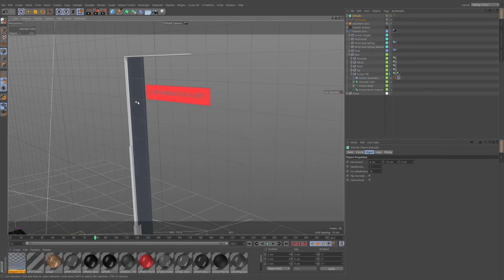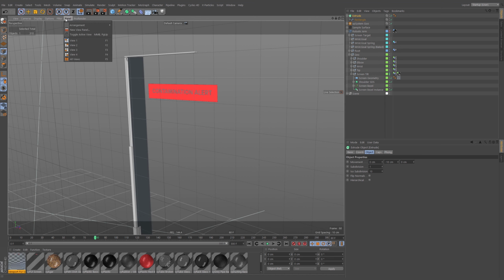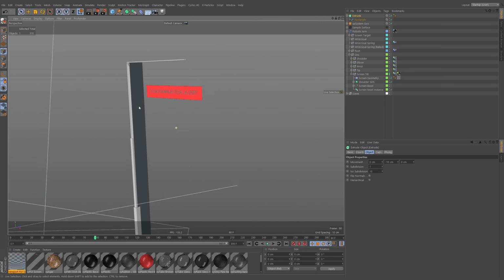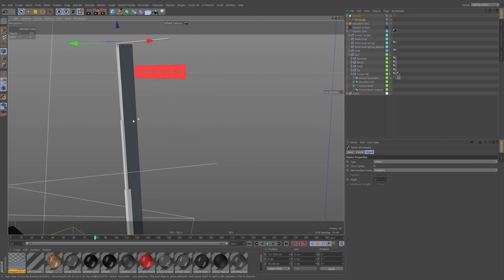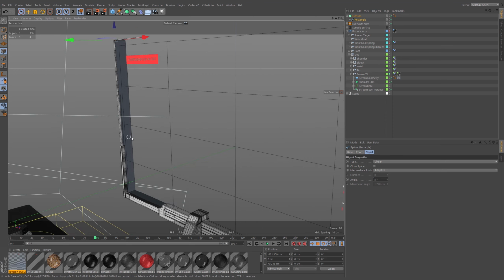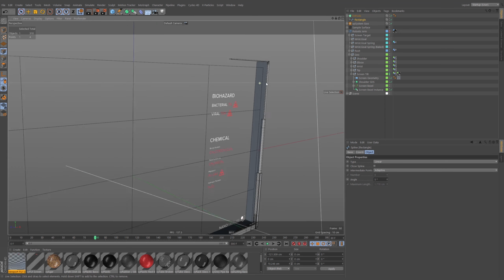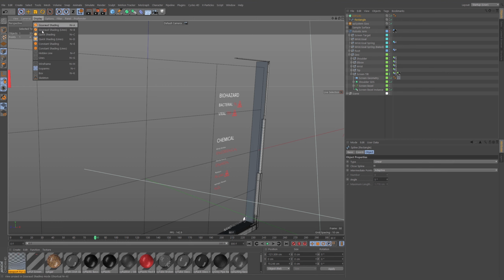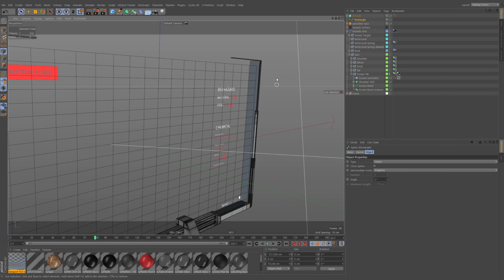But first things first, let's hide our grid. So filter, hide the grid, and at the moment there's going to be no subdivisions between each of these points because it's currently set to adaptive intermediate points. If the angle is less than 5 degrees, add another point, whereas clearly we've only got 90-degree angles. And also we need to make sure we're showing lines, so display lines, and we're in an isoparm mode. Display wireframe, and there we go.